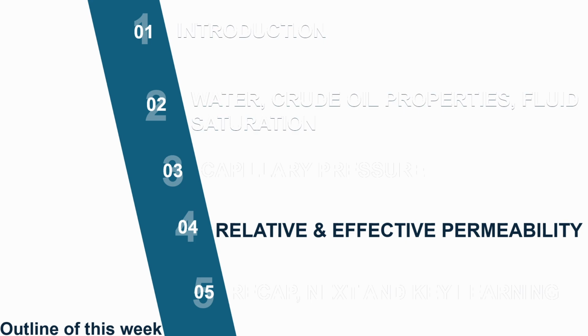Now we move into the heart of multi-phase reservoir flow, effective and relative permeability. If absolute permeability tells us how easily a single fluid flows, relative permeability tells us how fluids compete when oil and water, or gas and oil, flow together.